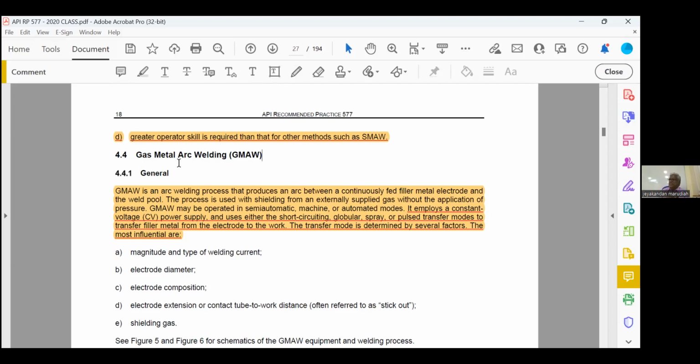But the problem is, when you are welding a thick plate, because of low current, there may be a lack of fusion problem. You remember yesterday we saw in section 9, GMAW short circuiting welders cannot be qualified by radiography. The reason is the lack of fusion problem. Modified short circuit is the recent development to avoid the lack of fusion problem.